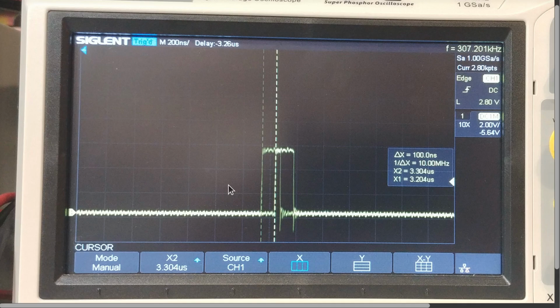My point there is if 100 nano becomes a significant percentage of error, like if you run it at 115,200 baud, this is on the order of 18% jitter, okay? You could probably get away with that in jitter. You certainly couldn't get away with it if the frequency was off by 18-20%. But you're pushing it, okay? So just be aware of this.